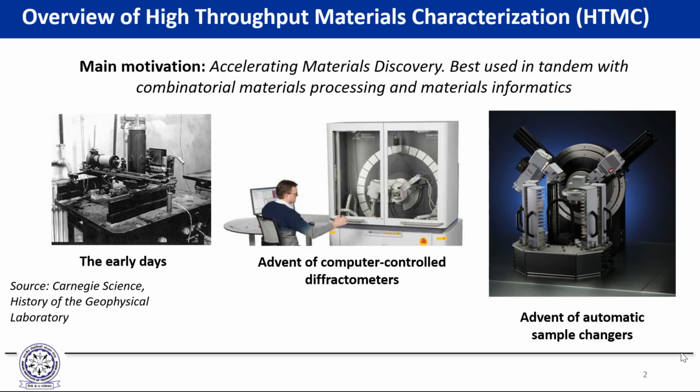Nowadays, we have got X-ray diffractometers which have got stacks like this. So these stacks are stacks of sample changers. You will see that you've got small shelves over here. Each of these shelves holds one silicon wafer, for instance, if you're putting your powder sample on the silicon wafer. What you basically do is program how many samples there are, and then this stack of shelves will slowly move upwards, and with every run being completed, the sample is shifted back to the empty shelf and the next shelf's sample is shifted to this stage over here.